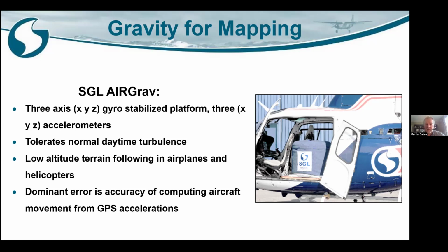We're actually measuring at a higher rate of like 160 hertz, but we end up correcting at 10 hertz. And then we downsample it to 2 for our final data after some filtering. But the corrections are done at 10 hertz. So basically, every tenth of a second, we need to know where we were relative to where we were a tenth of a second before. That's the accelerations that we're interested in. That's going to tell us what G's we pulled in vertical and horizontal as we were moving at that time, and then we can correct for that.